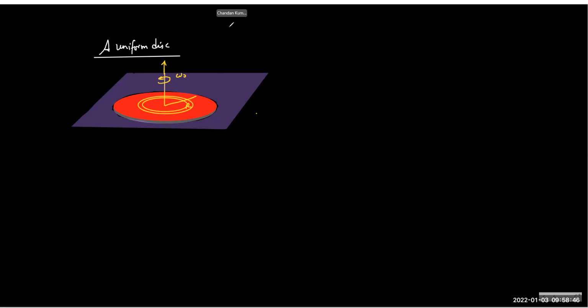So friction will oppose tangentially only. It will be tangential everywhere. Because the friction is tangential everywhere, the net friction force will be zero. So it will never create acceleration of the center of mass, but it will create a torque.